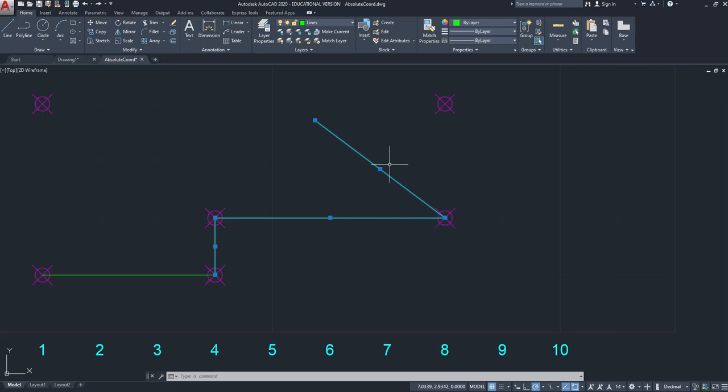The nice thing about AutoCAD, and this is opposite in Revit, is that if I hit escape here, I can pick one. I can click on a second object, and it keeps the first selection and picks the second selection. Revit doesn't do that. If I pick on one and then I pick on another, it unselects the previous one and just selects the current one. So I can click, click, and I can hit delete.